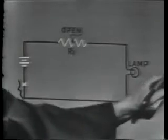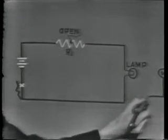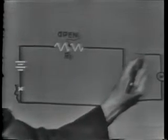Suppose this resistor looked all right from the outside, visual inspection wouldn't help. So how could you tell it was open? You could do this with either a voltmeter or an ohm meter. First, I could connect the voltmeter across the lamp. There would be no voltage present, and the voltmeter would indicate 0 volts.